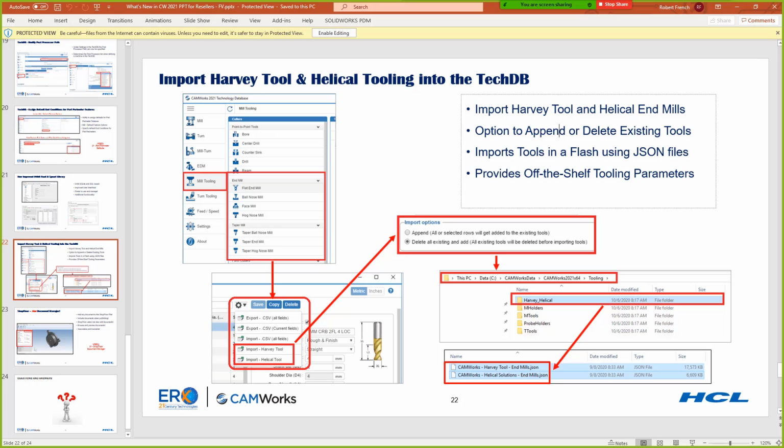Yeah, helical. Okay, and so helical tools are, and John Eichmann also chimed in here, helical tools are what VoluMill is based on. You guys might have heard VoluMill or adaptive clearing or high-speed machining. These are very fast, specialized toolpaths using a trochoidal toolpath, and if you're doing a lot of hogging out of material, VoluMill is a very powerful way to clean up all that stuff.